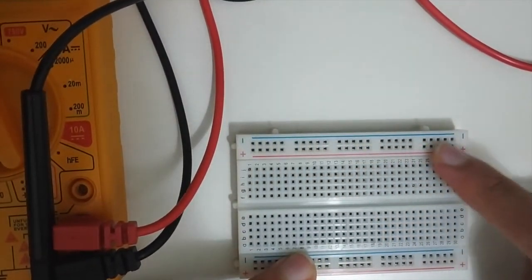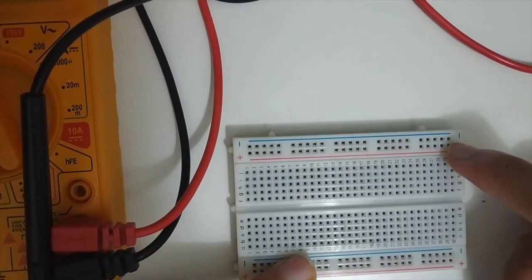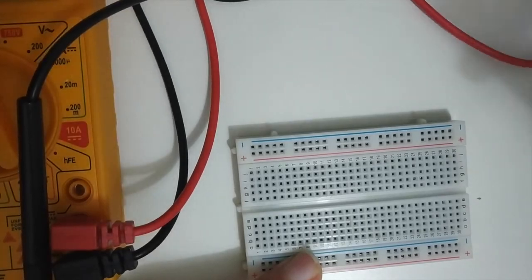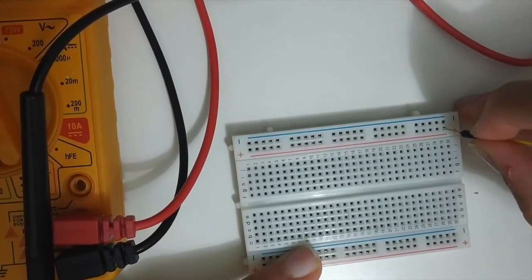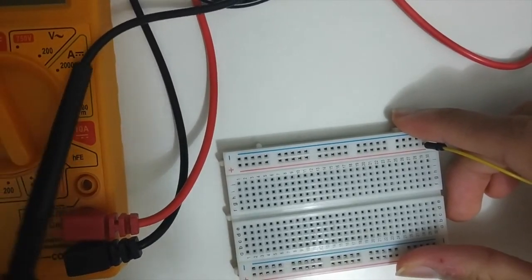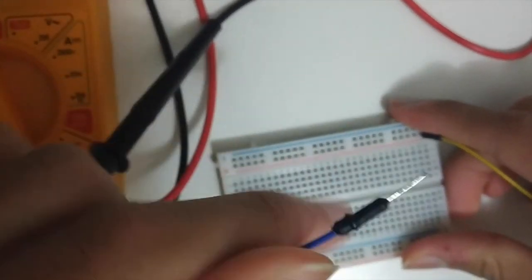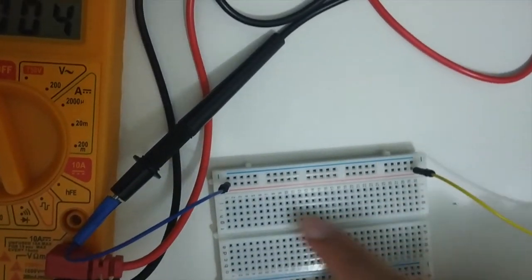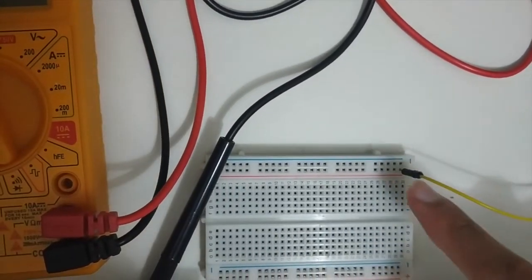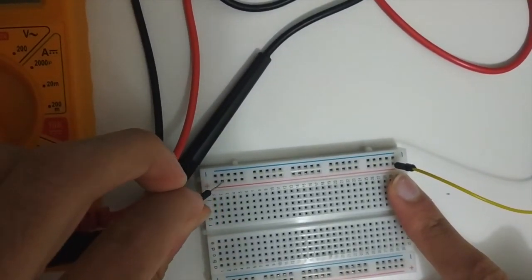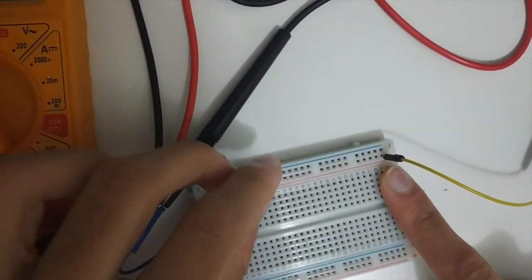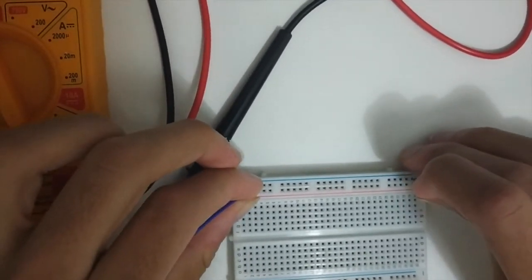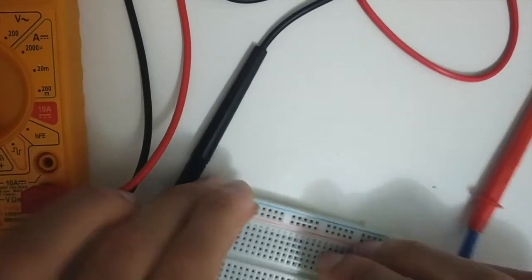So this is the power bus, and the contacts, as you might remember in the PowerPoint, run vertical for the positive terminal and the negative terminal. So if we connect this yellow wire as if it's 5 volts from the Arduino, and we connect this blue wire, and if we connect it here, the buzzer sounds, which means that they're connected. So 5 volts coming from here will ultimately lead to 5 volts coming in the blue wire. So that's how the contacts work there, and it's the same story for the negative terminal.